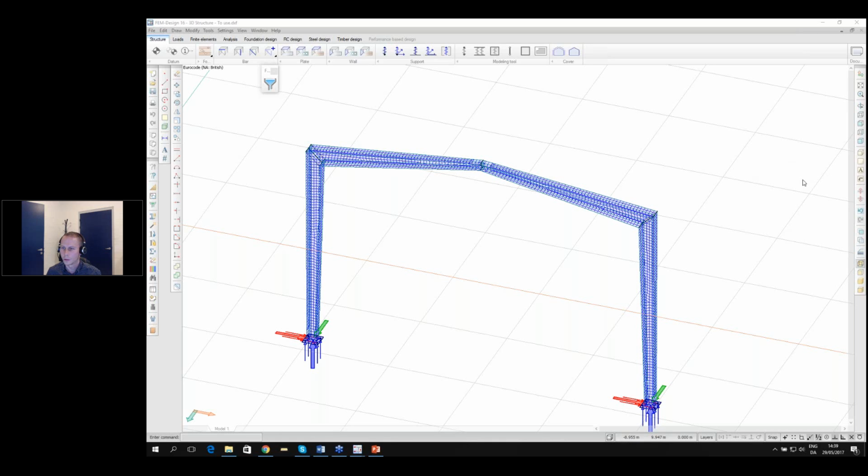I got a question here from Pierre asking what is the design load with regards to web buckling for this structure. The design load is actually, if you imagine you put a load of 1 kilonewton per meter, or 1 kilonewton point load, whatever, then your critical factor on the stability analysis, if the critical factor is 1.5, your critical value is 1.5 times your load, which was 1.